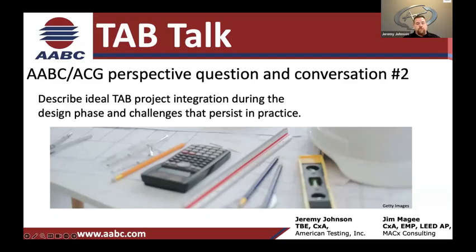it's really paramount to get that information out now, because if we're getting a job and we're not hitting some of this QA/QC, if you want to call it that, where we're actually another set of eyes looking at something as far as how it's practical to balancing, how we are going to overcome things, or how do we eliminate or mitigate as many challenges and adversities? How do we minimize TAB action lists or issue logs or resolution logs or whatever you want to call them, right? How do we minimize that so when we get to the balancing part of the job, there's things that we can look at and see ahead of time, and this is an experience related thing too.